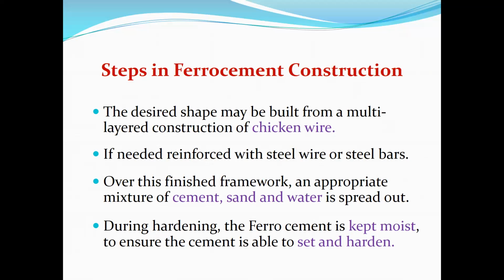And over this framework, you then apply the mixture of cement, sand, and water, and then it will be subject to hardening. During the process of hardening, the ferrocement should be kept moist, the normal curing that we do in conventional concrete, so that the cement is set and gets hardened.